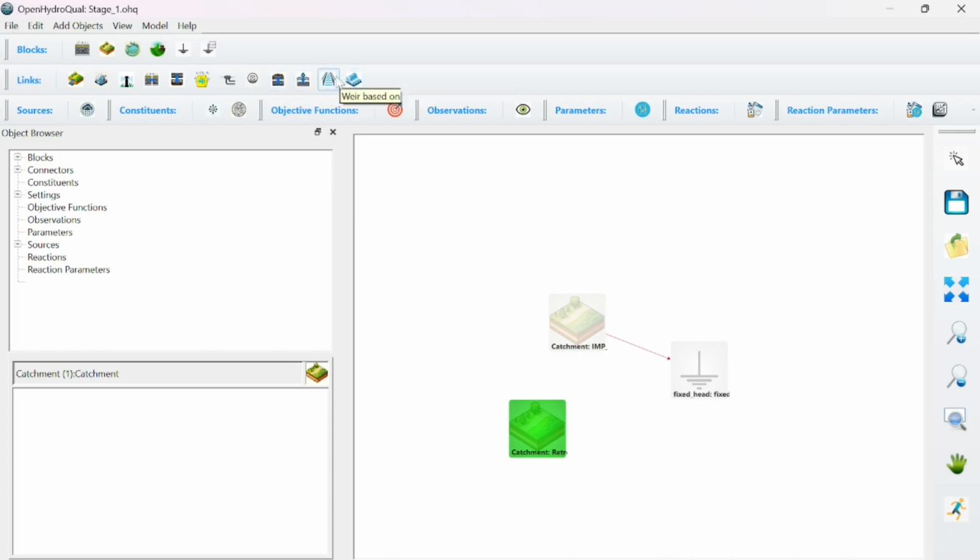There's a wide channel. That's just a channel that is wide enough so that when we calculate the hydraulic radius, we can ignore the depth of water. We can ignore the wetted perimeter due to the contact between the water and the walls. Anyways, and then we have a weir. That's the one that I'm going to use. So basically, it's a weir based on power law rating curve. Okay, so that's what I got.